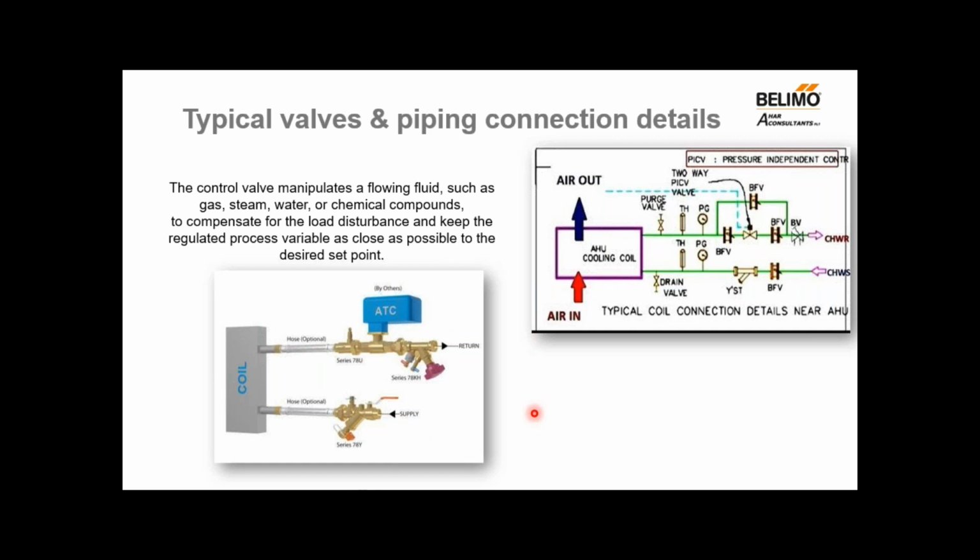Normally, there is no flow measuring device to actually measure the flow, as the flow meter is quite expensive. So how do we know how much flow is actually going into the coil at different cooling coil loading? We cannot do that, right? Many people think that overflowing the coil will improve capacity, but that is actually a myth.